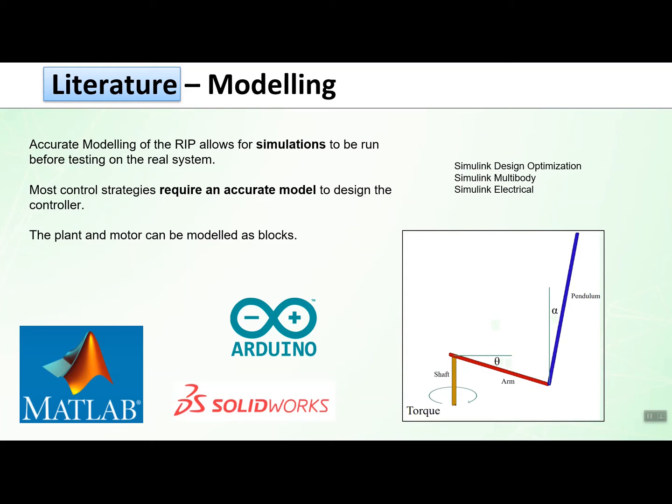These are some of the commonly used programs for modeling. Simulink offers many toolbox add-ons which can make the process easier and more accurate. For example, one method found for modeling a motor involved recording the motor's response and using Simulink's design optimization toolbox to emulate the response and create a model.